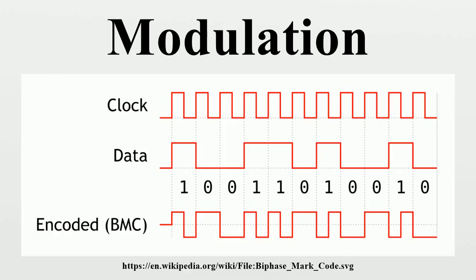At the receiver side, the demodulator typically performs band pass filtering, automatic gain control (AGC), and frequency shifting of the RF signal to the equivalent baseband I and Q signals, or to an intermediate frequency signal, by multiplying the RF signal with a local oscillator sine wave and cosine wave frequency. Then sampling and analog to digital conversion.